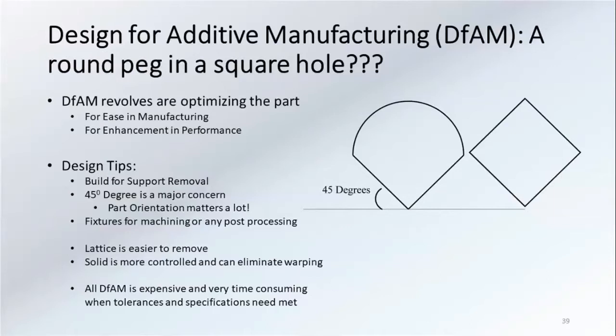The other thing you can do is if you're building a hole that you know you have to CNC later, don't build it, because it'll make the CNC walk, and so you won't get as good of a hole if you're touching up a previously made hole. So just make it solid and just touch it up later on.